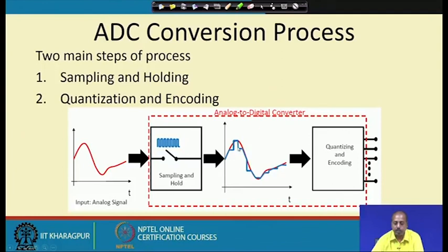Again it is closed from this point, so you do not get this red part, again you get it from this portion. That way, whenever the switching gate is closed, you get the analog signal fragment available at this output point, and whenever it is open, it does not get the thing.